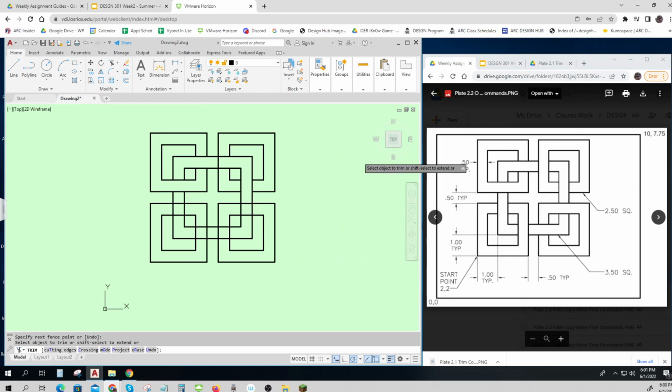If you want to see how big something is, you can click this dimension button and click just to make sure that you got the dimension right. And then Control Z. Or you can type DIST, enter, click, and in the little box it tells me, or it tells me down here. So those are two ways to verify that you've gotten it right. I don't want to see all the dimensions on your drawing. I just want them to be right.